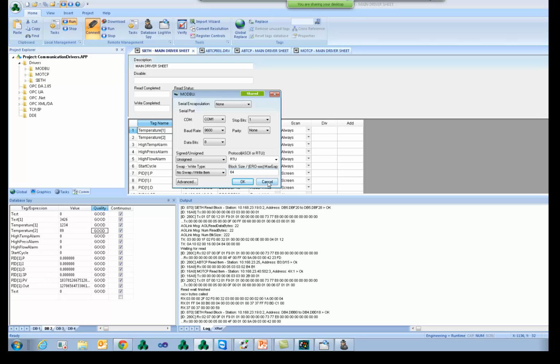All right, so look at this. You're gonna see most of the messages here. Of course, if you configure the wrong COM port, as you try to open it, it's gonna fail. Or if the COM port exists but you're not connected to that channel, we may time out. Timeout is when we send a message and the PLC doesn't answer. If I misconfigure a station here, I also will not be able to connect to that PLC, so we're gonna have the message here that the connection failed.